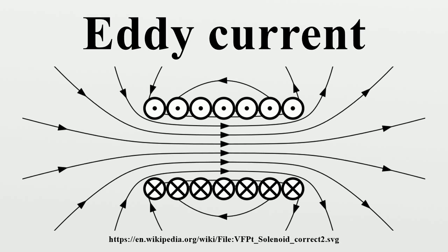Due to eddy currents induced in the surface by the moving magnetic field, this effect is employed in eddy current brakes, which are used to stop rotating power tools quickly when they are turned off. The current flowing through the resistance of the conductor also dissipates energy as heat in the material. Thus eddy currents are a source of energy loss in alternating current inductors, transformers, electric motors and generators, and other AC machinery, requiring special construction, such as laminated magnetic cores, to minimize them.